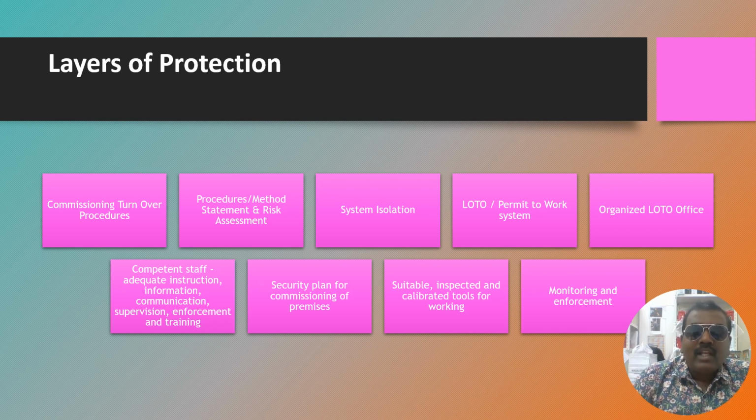The reason is, if you energize here, the power supply will flow wherever the breaker is in service condition, the electrical supply will flow till the end. So this might cause an incident or fatality inside the site. So to maintain a safe work environment, we are locking the downstreams one by one.